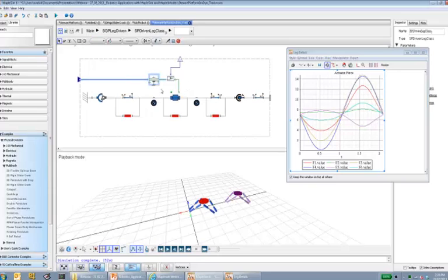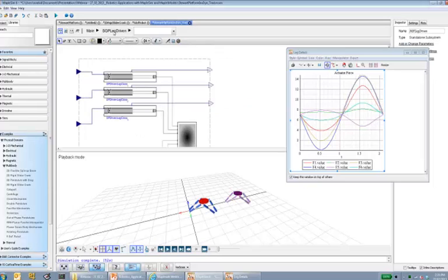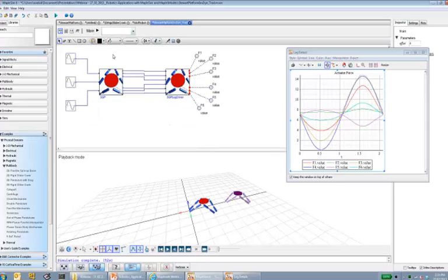By doing that, we are using the solution of the inverse kinematic, and now that we are extending each leg according to the value that we have just calculated, we can utilize the dynamic equations and find out how much force is needed to basically adhere to that constraint that we are applying. And that force will be the solution of our inverse dynamic. So with this scheme, we have solved the inverse kinematic and inverse dynamic.